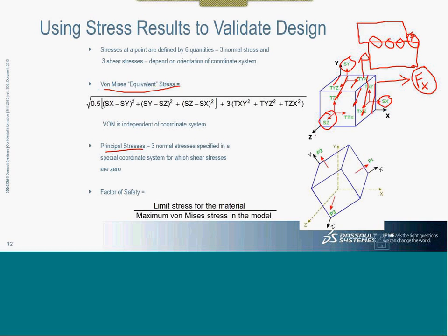Sorry, it is plane YZ, XZ. Where is XZ here? Okay, it is represented a little bit differently in this image, but the basic idea remains the same. The section over here, which is actually parallel to the application of force, by this cross section will give us shear stress in this plane. On the other hand, the force divided by this perpendicular plane will give us normal stresses. This needs to be understood.